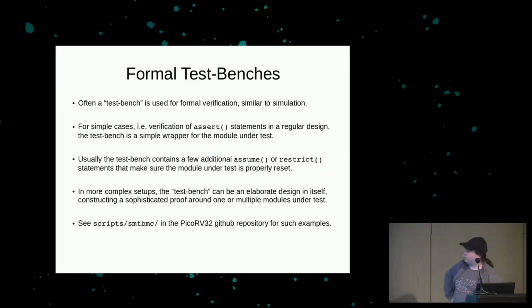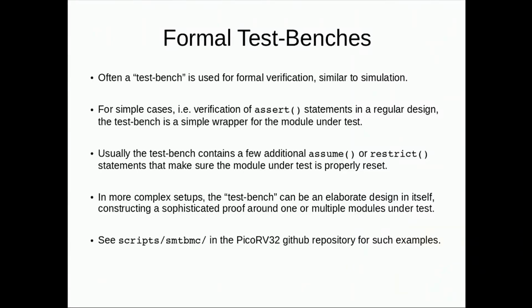So in simulation, we usually have a test bench that creates input signals for our circuit and stuff like that. With formal verification, we also sometimes use test benches. However, those test benches don't play through one possible path with our circuits like a normal simulation test bench does. Instead,